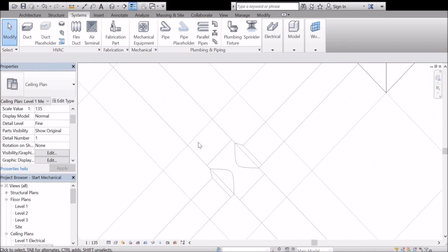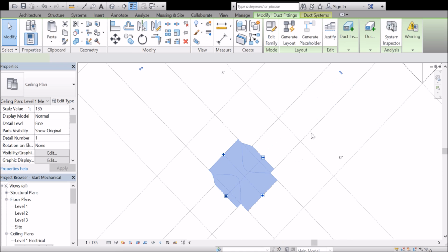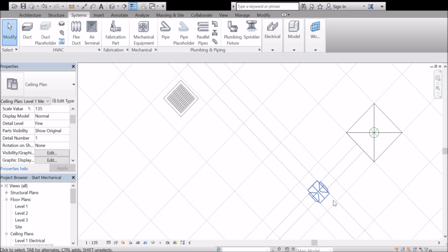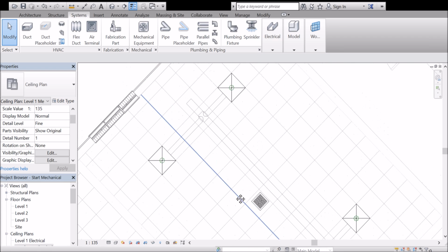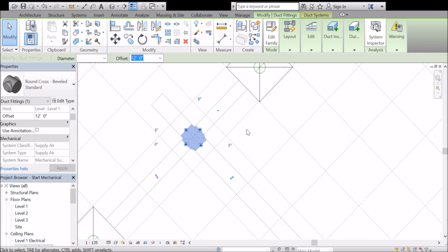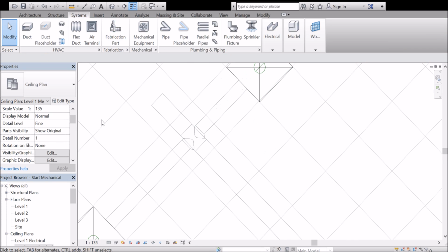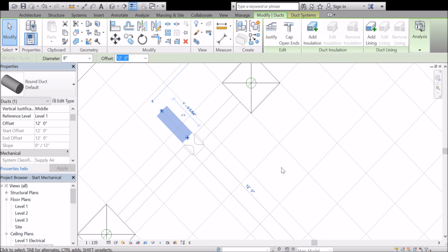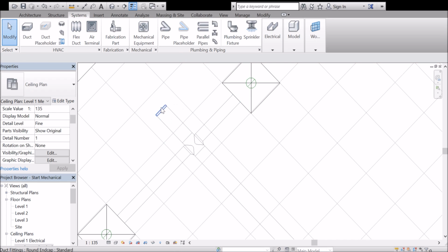And then if I want to be real particular, I'll flip this around right here just because it looks a little bit better. When they actually install that fitting, it would be facing that direction. Same thing for this one up here. I'm just going to flip that. Then we got two more things we need to do. We need to throw a cap on this section, so let's just go ahead and click that. And up here on this upper menu, there's this cap open ends button. If we just click that, it automatically caps that duct.